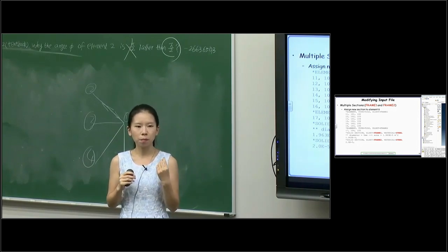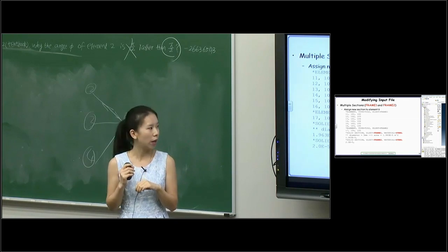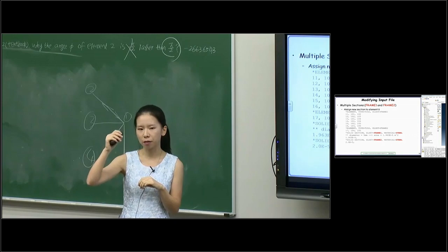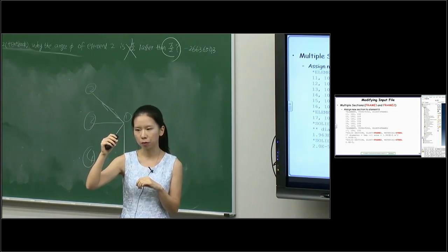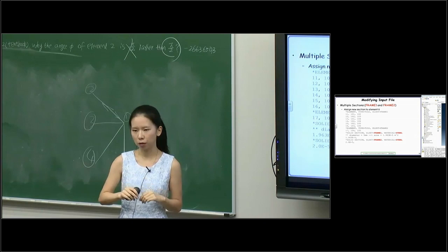But some members will have very high stress, and some members have very low stress. And I have an allowable stress. So for the member whose stress is higher than the allowable stress, what should I do? Increase cross-section area, right? Make the stress decrease and make it below allowable stress.